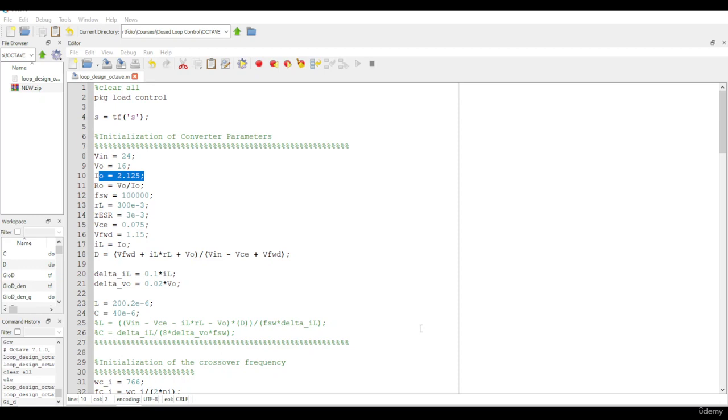Before moving on to the next section, I want to address this output current here, which is obviously different to what was stated in the previous section. It doesn't have a large effect because this system is designed to be robust, i.e. the output current set point could be changed in the firmware as you like, within a reasonable range, and it will not make the system unstable.